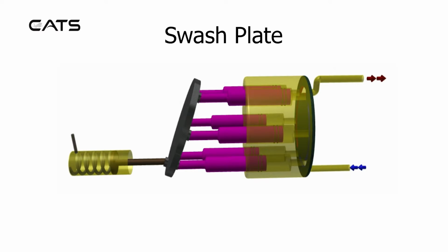Systems can be used to detect pressure downstream, and if there's a fall in pressure, the swash plate can be manually or automatically adjusted to increase the throw of the pistons, therefore sending out more fluid downstream.